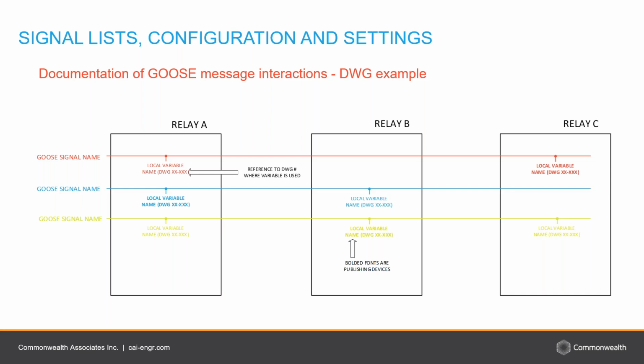And then the logic variable and where that's coming from, if you have a logic diagram to refer to, can be added as a drawing reference to this. So you can see at a glance what the signal name is, where it's coming from, where it's going to, and also have a reference to go back and look at the logic and dig into more information about that signal. So this is one way that I've seen it documented.